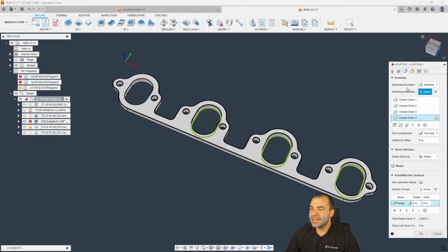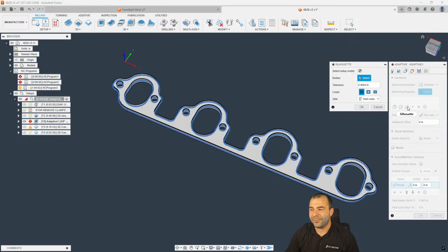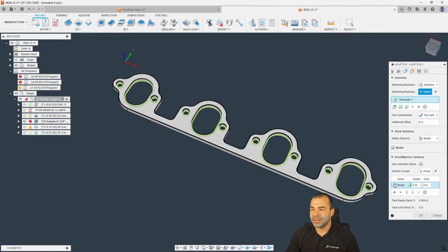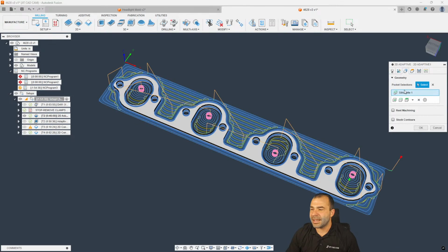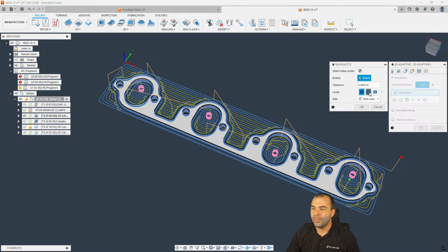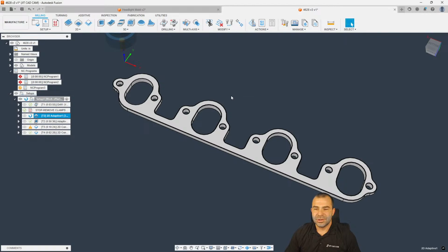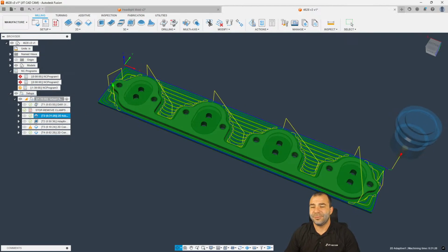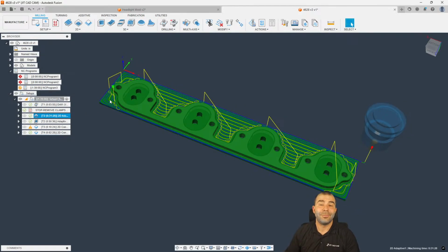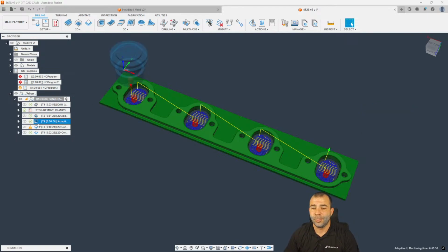And if I had to guess right, he's going all the way through the middle sections. So again, prepping him for the ability to actually do this in a quick fashion, we could say inner loops on this actual profile. And then on the other one, we could swap this out, and instead of doing a silhouette all, we do outer loops only. So as you're seeing, instead of me picking edges in 2D, which I'm not a fan of, I could actually take the information that he's using and automatically define things based on a silhouette of my physical part, and then use that silhouette either inside, outside, or both.